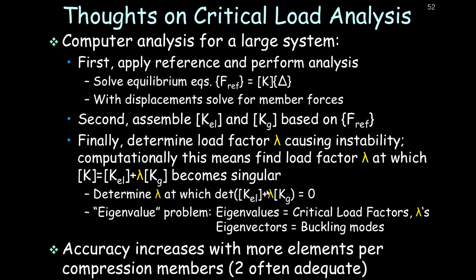Usually, the recommendation we make is you take a simple problem, and for that particular piece of software, use 2 elements. Did you get the right answer? No, you're probably off by 3 or 4%. Use 3, 4, 5 elements, and you keep increasing the number of elements until your solution won't change. That's what we're doing there. We're just using more and more elements until we know our solution is accurate.